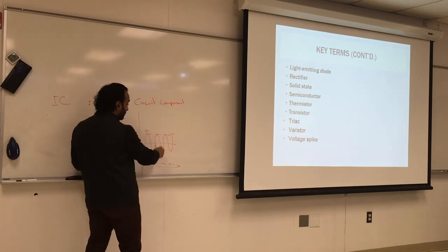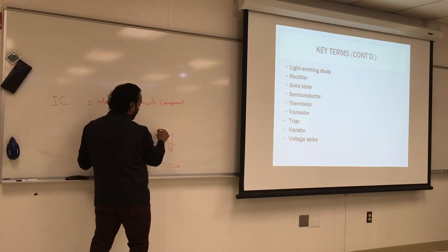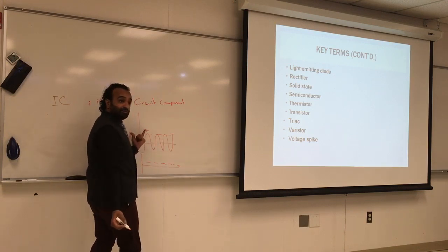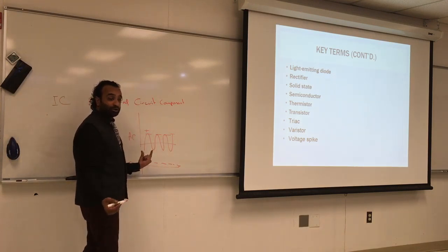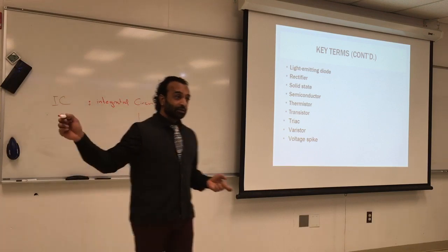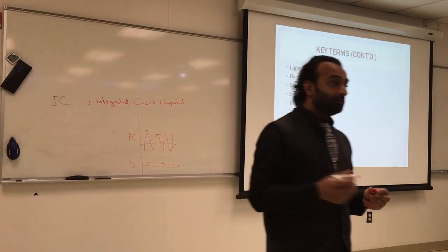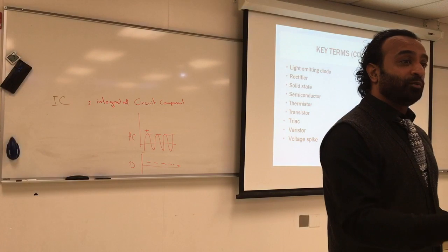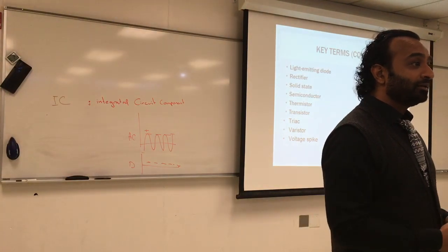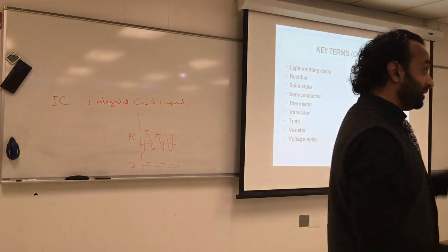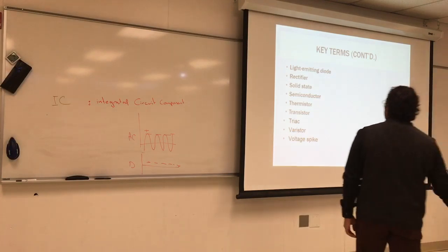So the diode will only take the ones going up. So you're going to have peaks, and you combine those into a circuit where you get only the peaks and make them constant. Put them in a small amplifier, and it will become DC. And you also have to reduce the DC to the right amount of voltage.